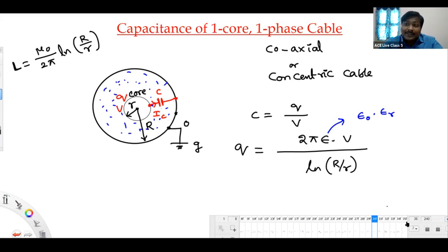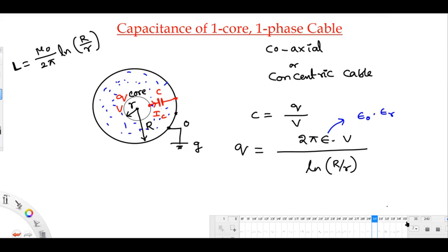So the capacitor will experience a voltage close to zero. Whenever the fault gets disconnected and comes back to normal condition, that arc will disappear. The spark gap arc will disappear, and it will act as an open circuit. Yes, and your current will flow through the capacitor.